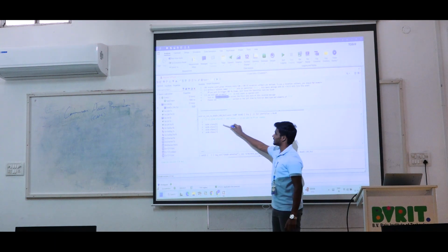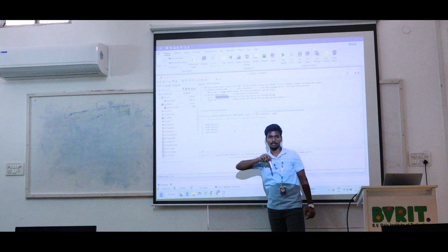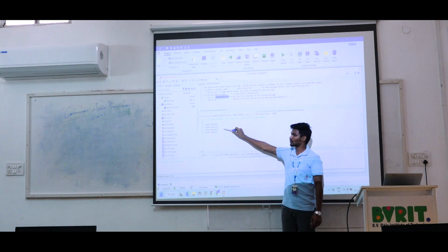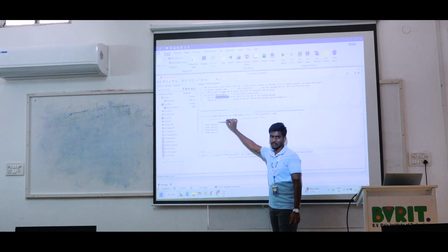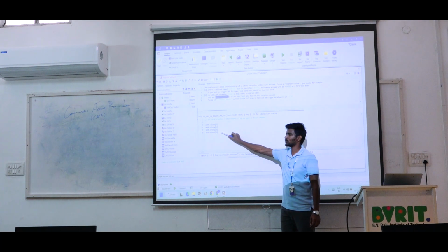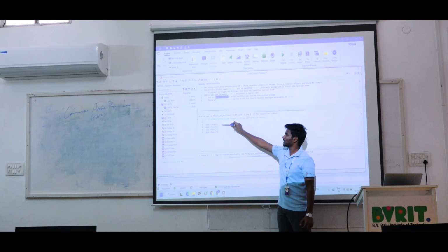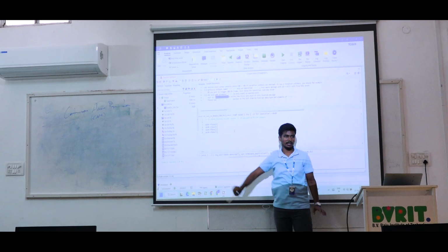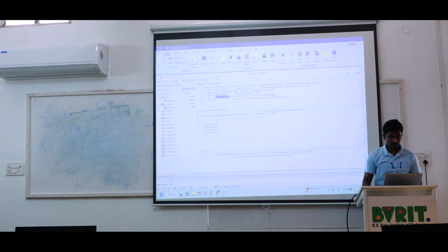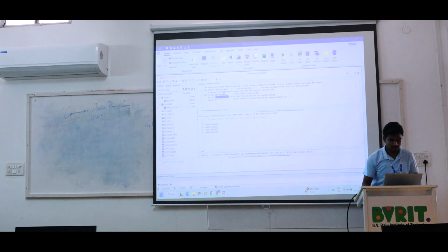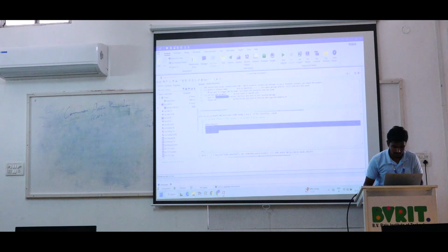Now this is mentioned again as byte 1, byte 2, byte 3, byte 4. Okay, which means it is accessing the first byte of message 20, the second byte of message 20, the third byte, the fourth byte of message number 20. So now it is the vehicle speed, the transmission gear ratio, the gear position, the clutch position, like that we have to take it. Now we just transfer only the first byte, the vehicle speed, correct, in our transmission set. So we are going to work with byte 0.